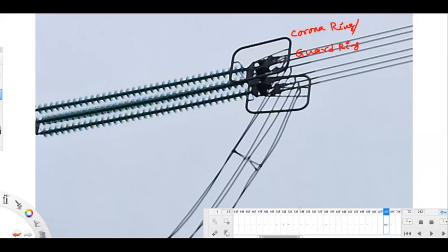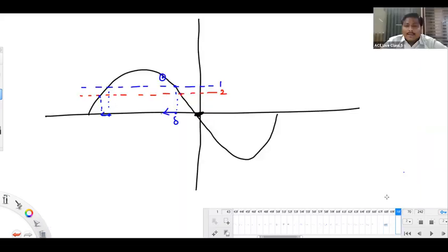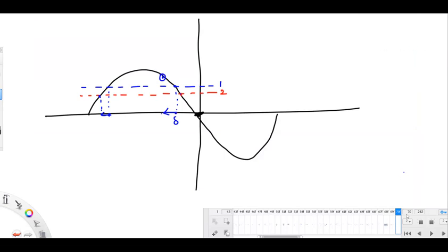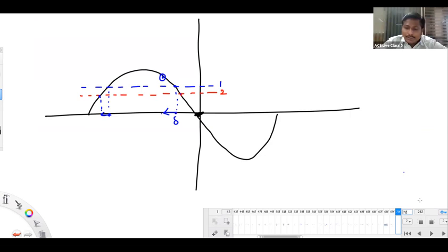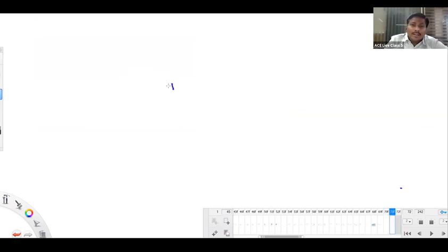Tell me what's your next term? Sir, in overhead line for doing the symmetrical, we are using the transposition. Transposing the line. We are having the concept in the cable also, sir. That is called as bonding. Transposition only we do in cables also, but that name is called as sheath bonding.